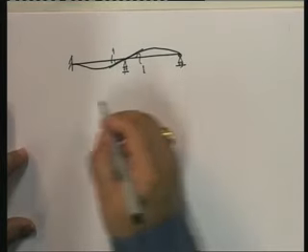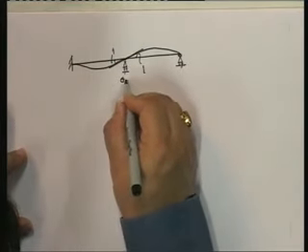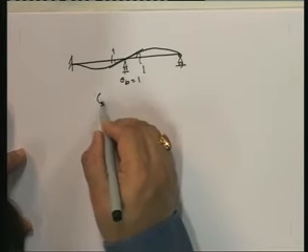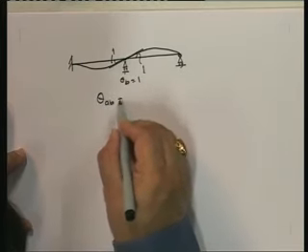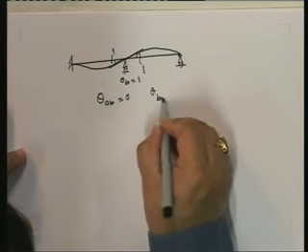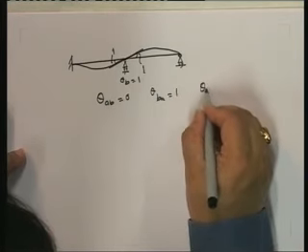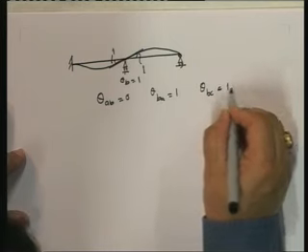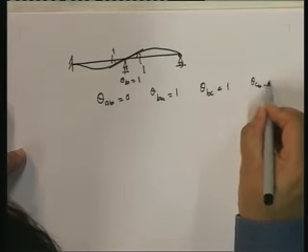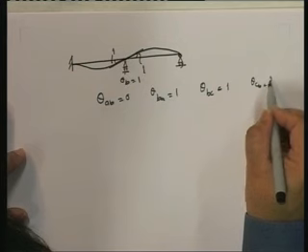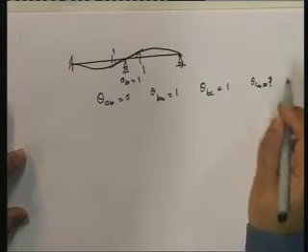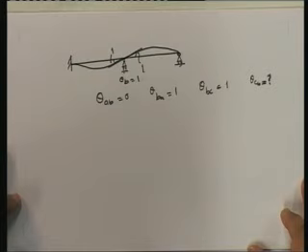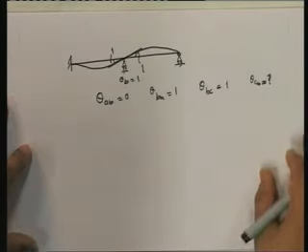So if I put this, I get that for theta B equal to 1, theta AB is equal to 0, theta BA is equal to 1, and theta BC is equal to 1. Theta CB I don't know and I don't care, because theta CB is not going to get into my force-deformation relationships anyway. So once I have that, I can put down the expressions.